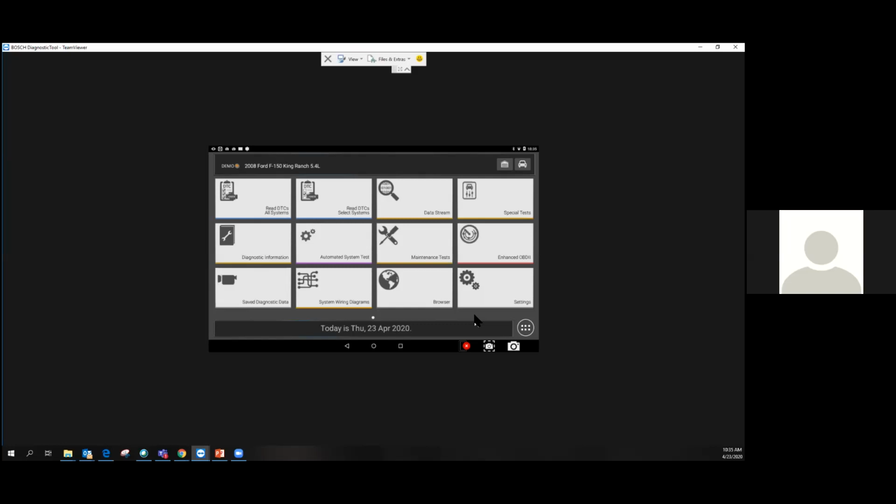You know, we've been repairing cars for a long time. We kind of rest on, oh, I've done this 100 times. Why would I bother looking at the repair procedure for it? But as we should all know by now, the simple act of replacing the windshield nowadays has become a lot more comprehensive a procedure with all these lane departure systems, rain light sensors for the wipers and the automatic headlights. It's not so simple anymore. And so we don't want to rely on past repairs. We want to look up that repair information and make sure there's not something updated on that. And that's going to take time. We want to be able to log that. We want to be able to document it.